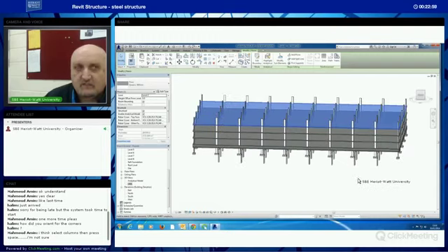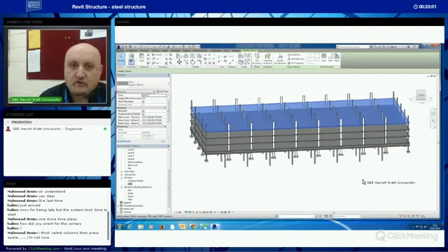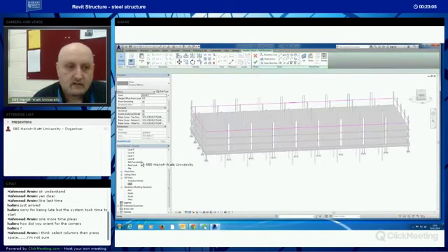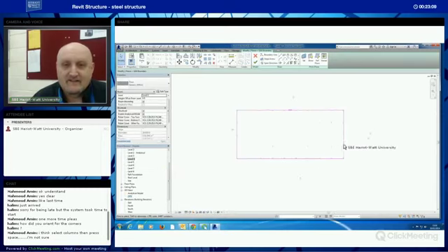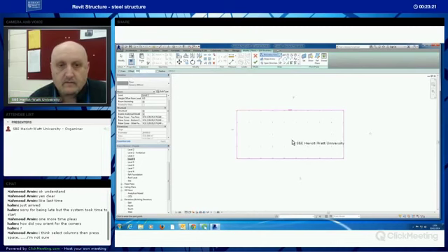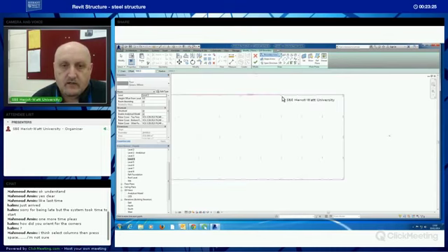And this one, I'm going to foreshorten this floor profile. So I'm going to edit its boundary. I go to the level that I'm on, level 4, and I'm going to put in a new boundary line again with an offset of 500. The offset's always going to be the same. Oops, not 5,000, no, 500. And I'm going to come into somewhere, I think about here.